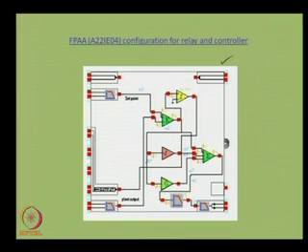So, here this part actually gives us the PID controller action and relay is shown over here. When relay is there, there are choices to design offline and online PID controllers based on the acquired plant information.